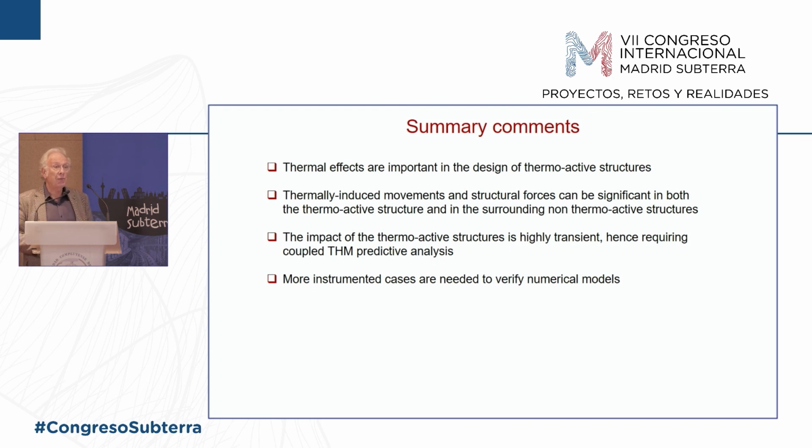But one thing we do need, and it's a plea to all of those people that are putting these things in the ground, is we need instrumented cases. And please, when you instrument, can you make sure the instruments are not going to be adversely affected by the temperature change? Because as you saw with the vibrating strain gauges and the optic fibres, they don't necessarily give similar results, which they should.